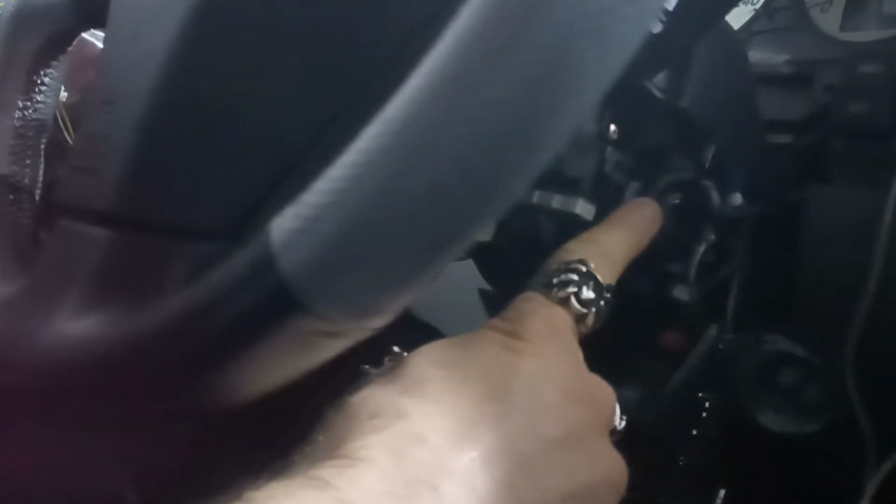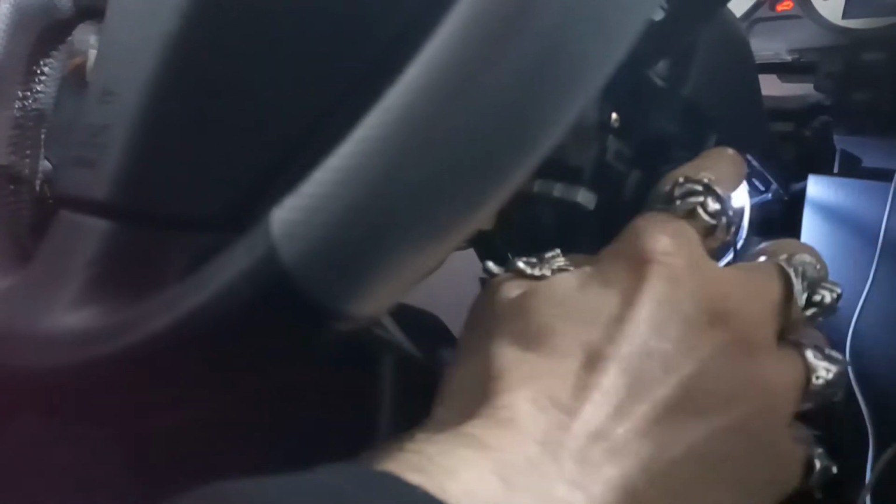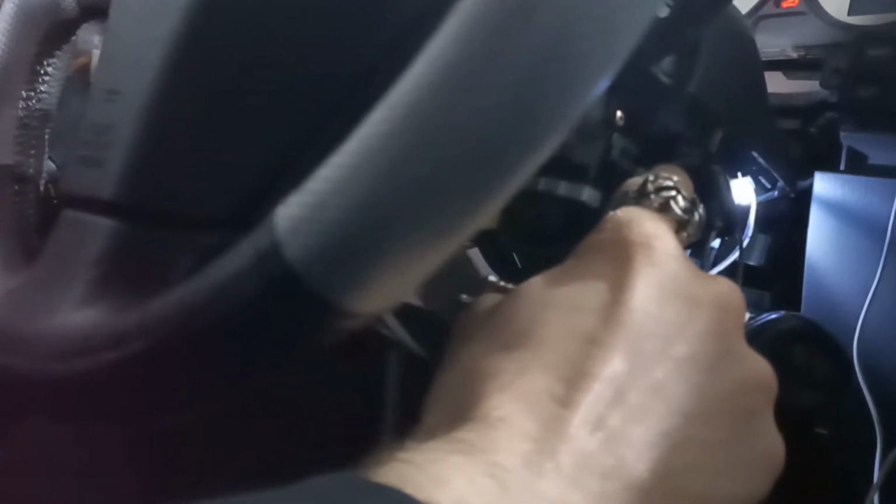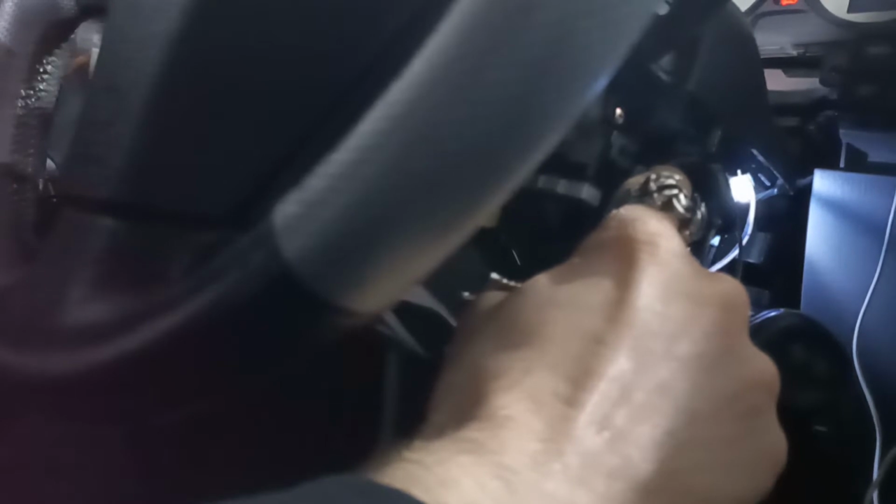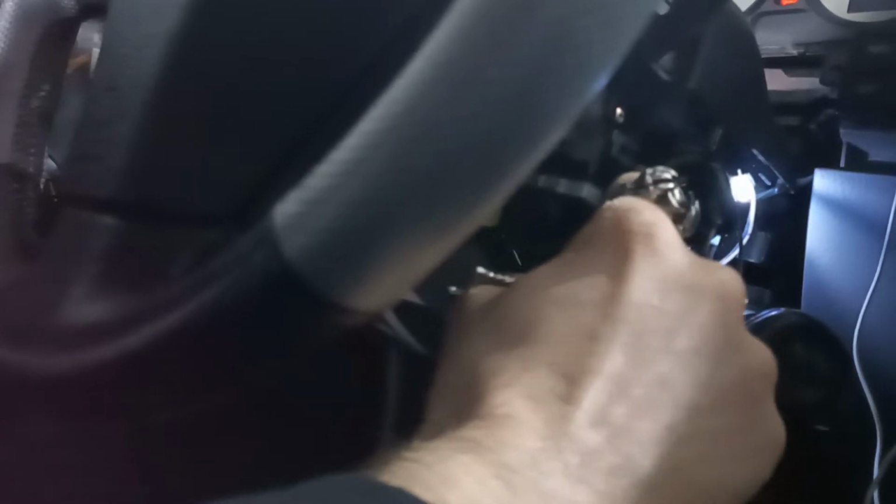For that you need two hands. First thing you need to do is turn off the auto. Then this needs to be not on ignition. And it's a good idea to open the door so you also have beeping, not only blinking. What you need to do: turn the ignition to on, then to off, and then auto on and auto off. Repeat that 3 times. So let's go.